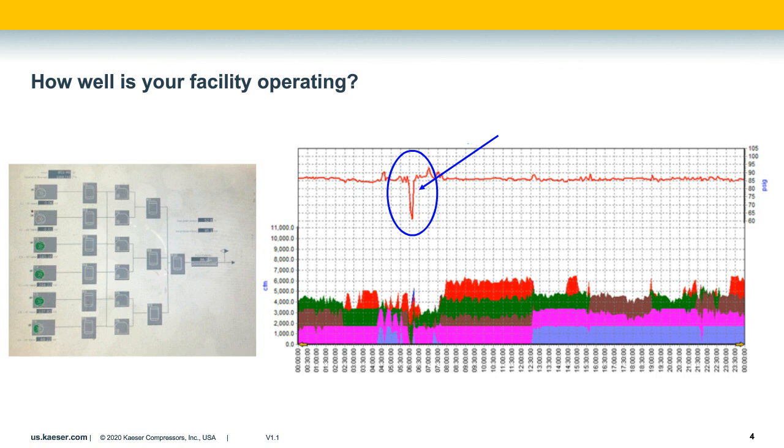At the time the pressure drops, the pink compressor actually drops out, turns off for some particular reason we're not sure of here in the data. But that seems to be the particular reason why we do have a pressure drop, and then other compressors don't come online, and therefore we have the issue in the plant.